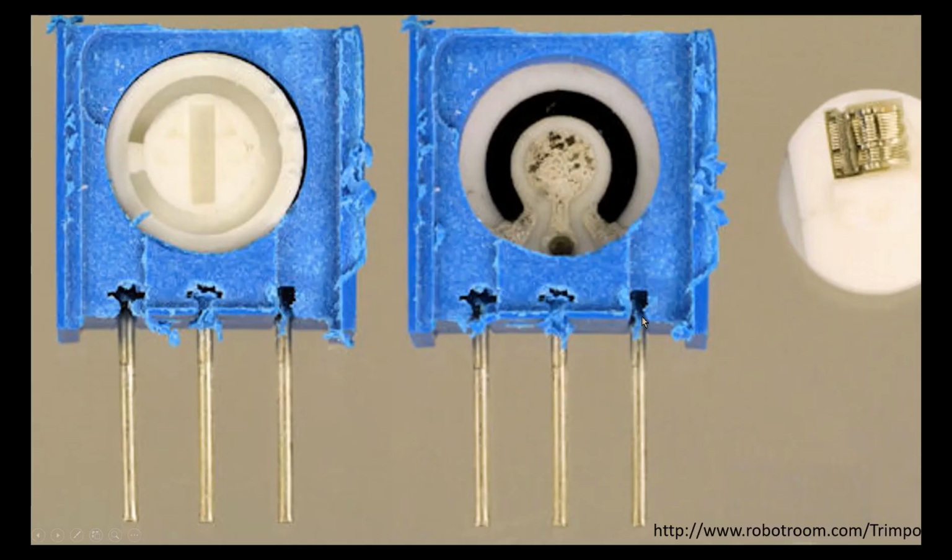If we look at what a real one looks like, it's very similar to the picture we just saw. So we have the resistive material connected to the two outer pins. The central pin is connected to this big pad, and then connected to the knob or whatever you're moving will be the wiper. So here we can see this bigger wiper makes contact with the resistive material, and then the smaller wiper makes contact with this central pad. So that's how you get the voltage from some point on the resistive material out to that central pin.